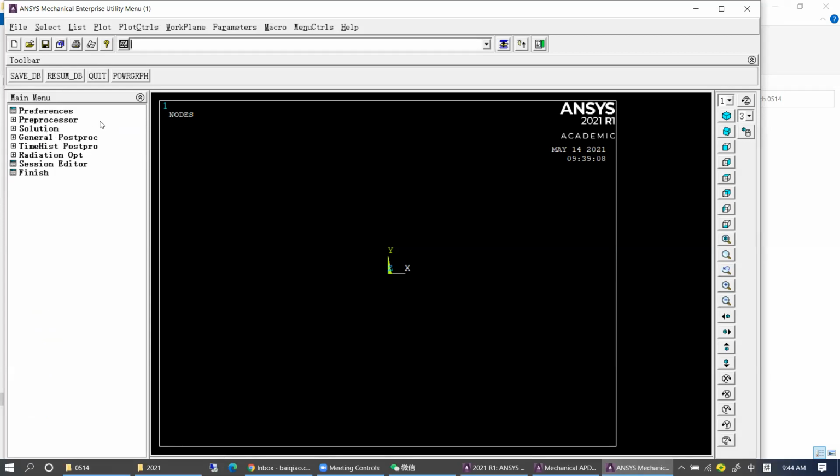And I would like to call your attention, there's no undo function in ANSYS, unfortunately. If you did anything wrong, then it's difficult. You cannot just do a simple undo. So there are different options. One is to completely start from the beginning, trying to remember what the correct steps were, reproduce them, and try to correct what was wrong. So that's why I recommend using a macro file.